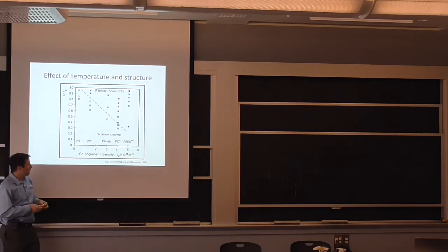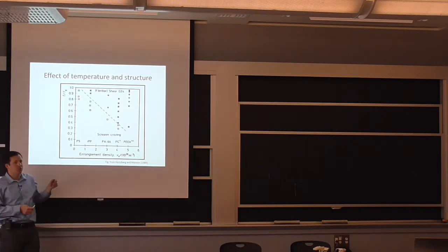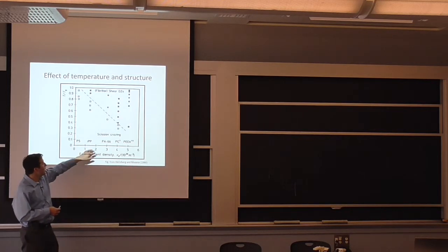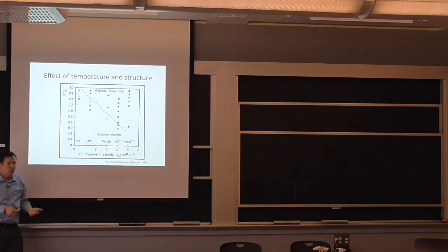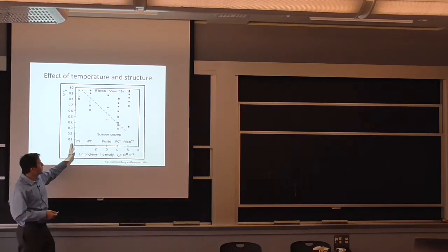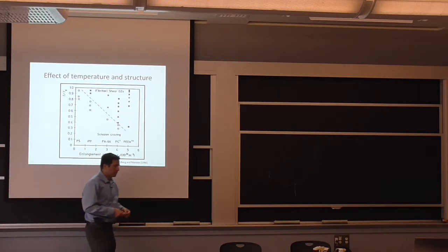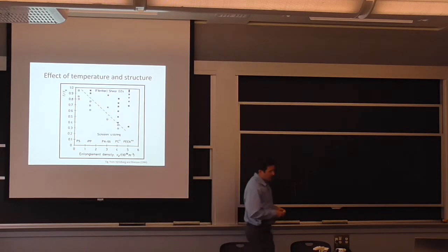So it's not completely arbitrary. There's always an effect of temperature. So polyamide, which is right in the middle, depends sometimes on either temperature or moisture. Moisture will reduce the glass transition temperature, so it'll make the nylon softer and less likely to form crazes than if it's dry. So those are the two main parameters that will allow you to know how it's actually going to deform.